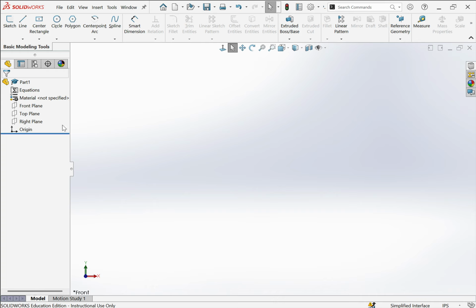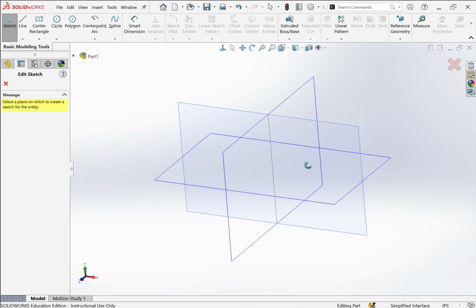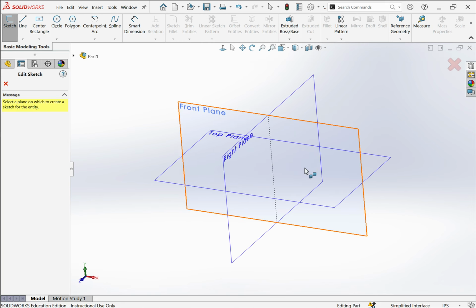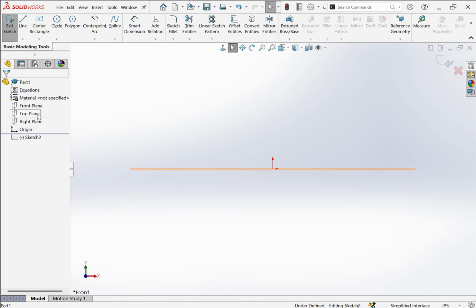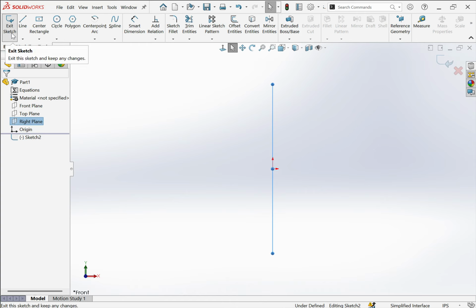then if you try to create a new sketch by clicking on sketch right there, and then use the middle mouse button by pressing the wheel down, that will get you this rotate. And then you can choose sketch planes from here, or if you go over to this tab, you can choose sketch planes. Once you choose a sketch plane that you prefer, in this case, I'm just going to go with front again. It shows down here what sketch plane I'm in. And then start. If you wanted to choose the top or the right, you'd have to be outside of sketch mode. So right now I'm in sketch mode, by looking at this button up here.